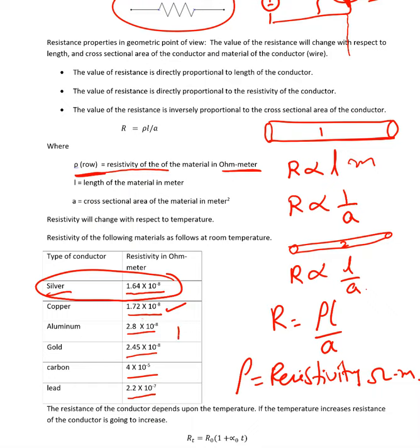We call them ACSR conductors. But we use copper especially in electrical motors, electrical generators, and transformers, because of space concerns. Their space is limited. If a conductor has more resistance, it's going to produce more heat, so there is not enough room to disperse that heat if we use aluminum.